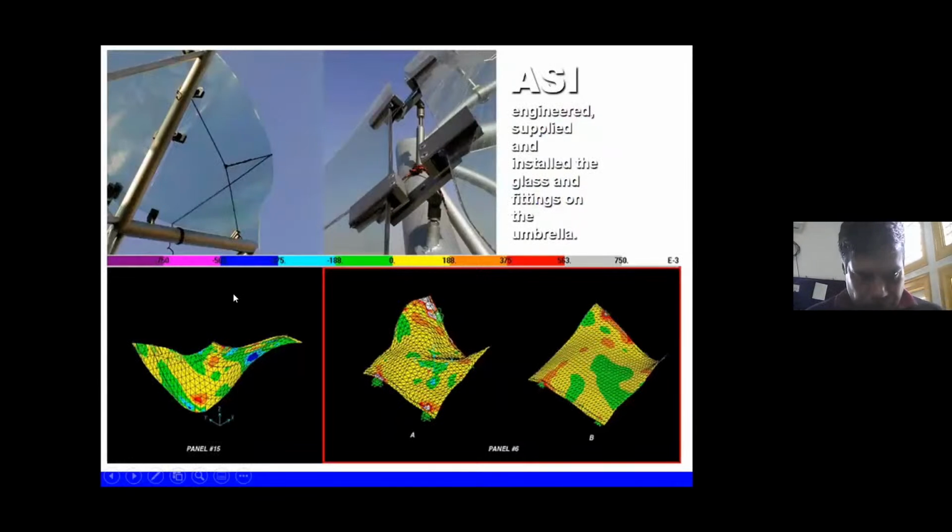Each glass is unique. And of course, this is the other thing I should tell you: we broke all 17 pieces of glass at one point in our whole process. Sometimes it was at the construction site, sometimes during installation. Our detail for the seismic joint used a neoprene pad, but this didn't have enough flexibility, and there were a lot of glass failures. This was one of the glass failures.